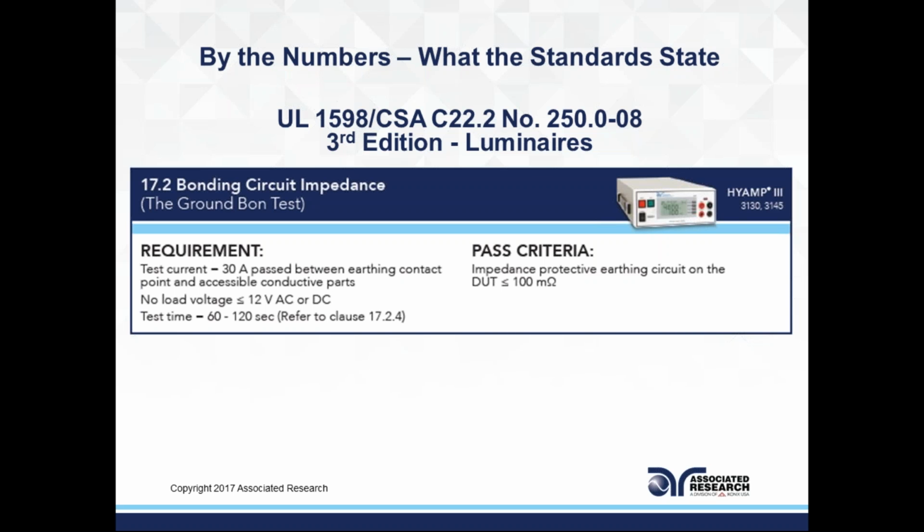Let's take a look at luminaries. It's a big market with the LEDs right now, where UL 1598 concerns luminary products. Now here the test current requirement goes up. So the current required here is 30 amps. Now during production testing, or during prototype testing in your design phase, this test time is listed here as 60 seconds to 120 seconds.